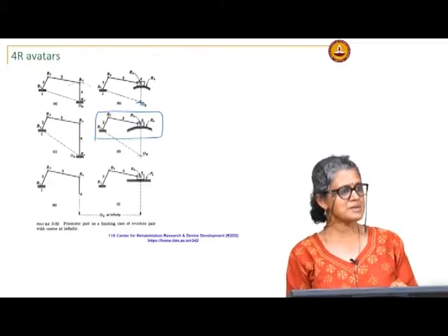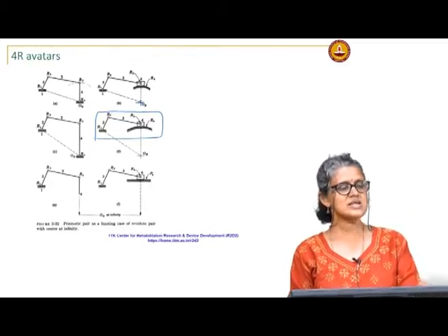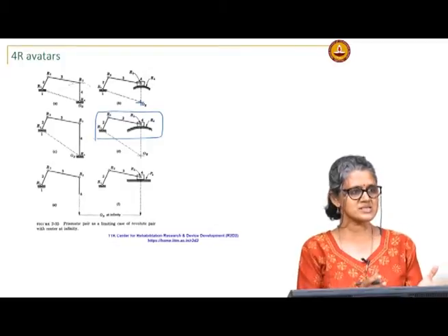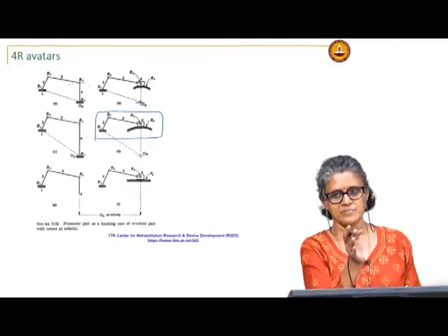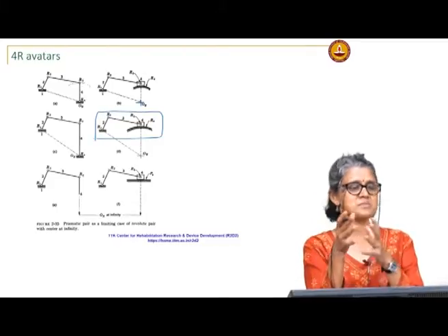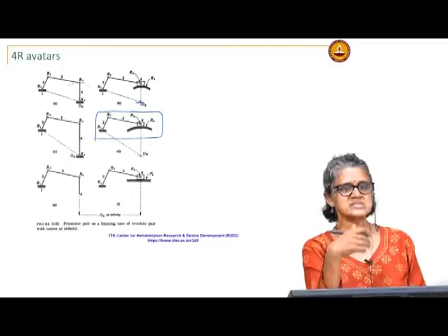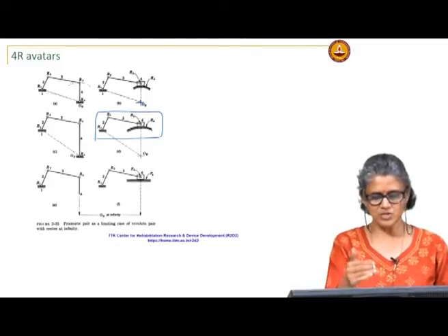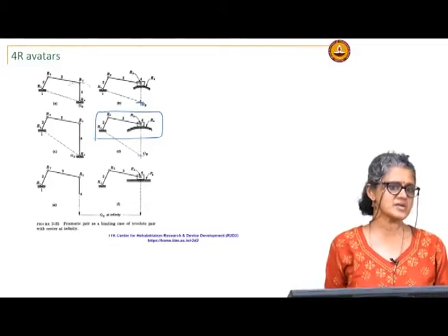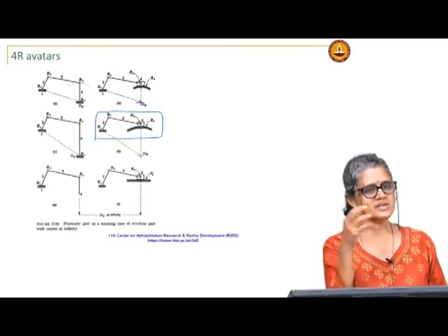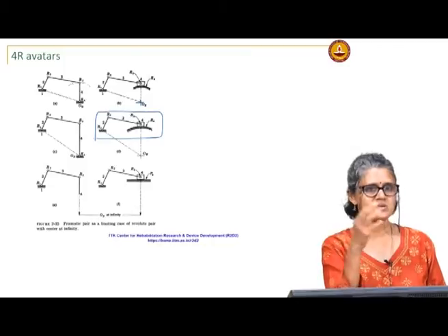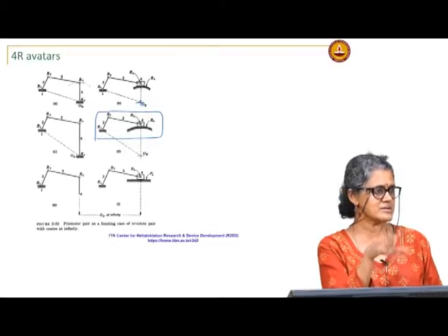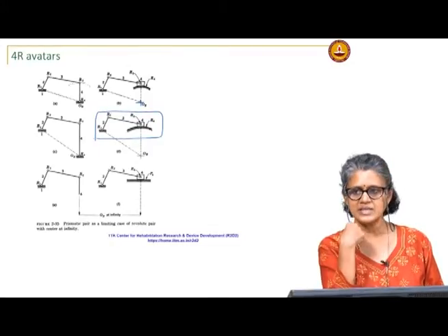But when you look at the kinematics of it, you are essentially looking at what is on the left hand side. Okay. So, it makes analysis simpler when you are able to identify the 4 bar in something that appears more complex. It makes the analysis a lot easier. Okay. And essentially the slider crank or the prismatic pair, it is just a limiting case of the 4 bar. That is why we always talk about the 4 bar and the slider crank in the same breath. We talk about them together, because essentially one is a limiting case of the other when the rocker pivot is at infinity.